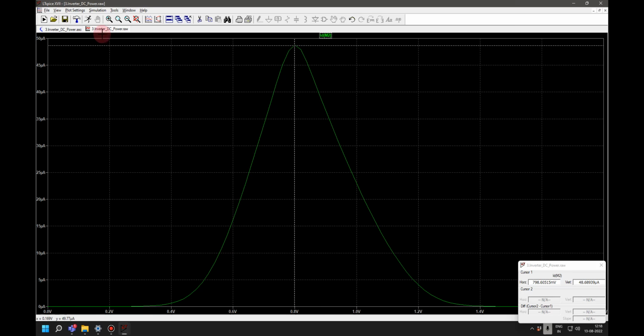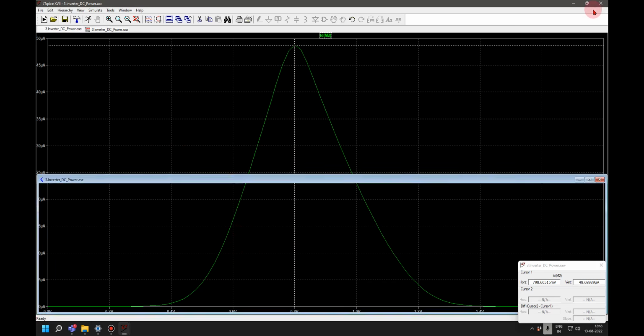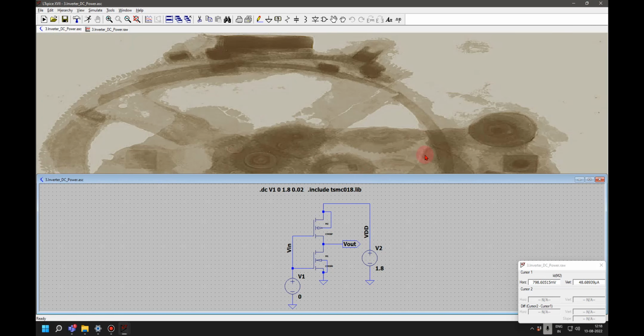This is the exercise which I gave you for your assignment. For the first one, since we are reading in detail about the DC characteristics, we will target and keep it at 0.9 volt. Henceforth, when we design bigger circuits, this slight 0.1 volt offset we will not take into consideration. So with that I will stop for today, and thanks a lot.